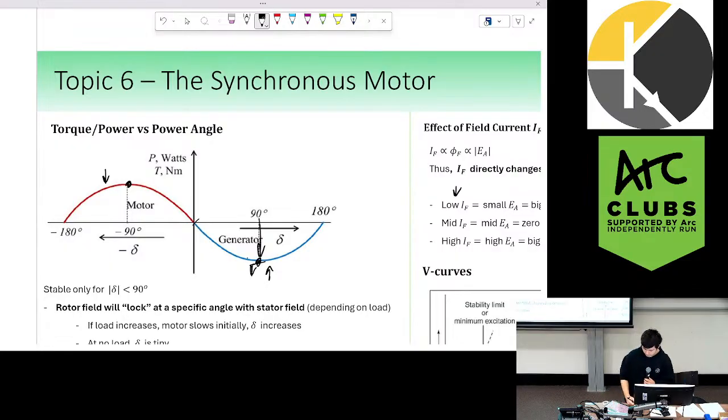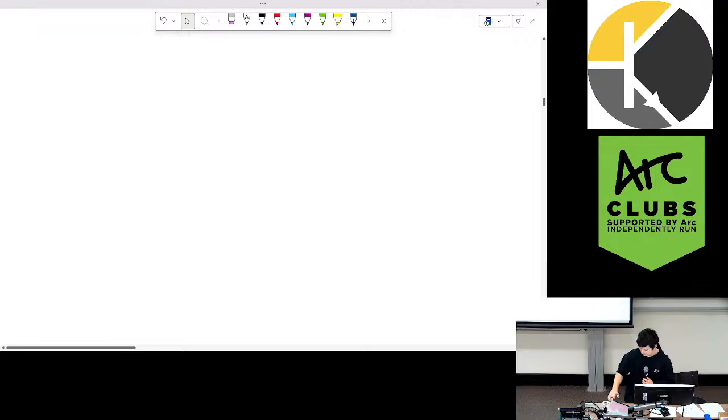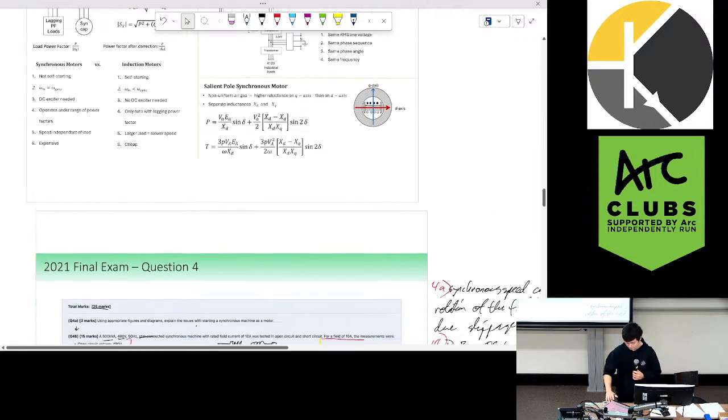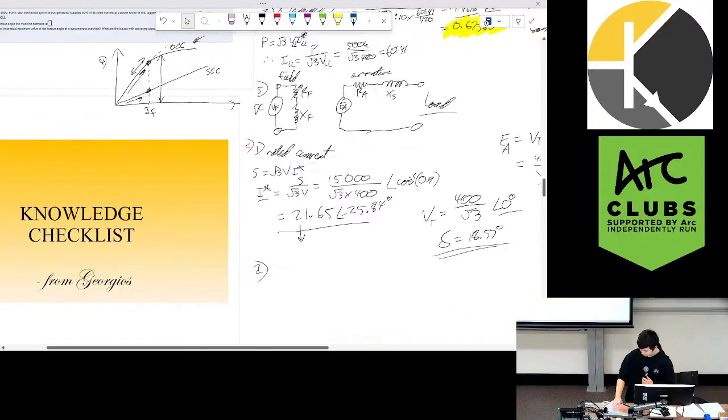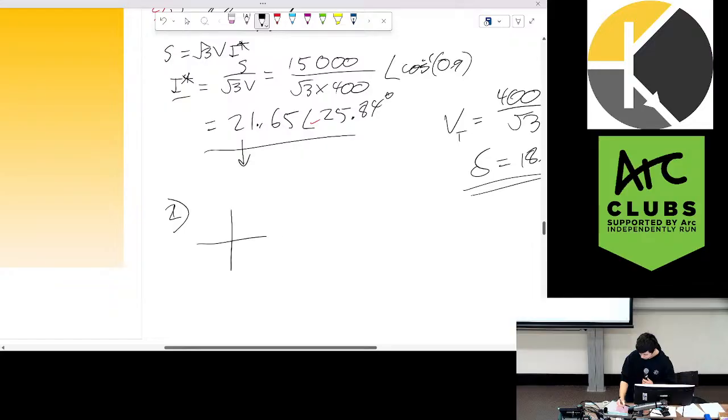So, what do we say? 90 degrees. Do we just say 90 degrees? Not technically. So, something to note is this is an electrical angle. It's not necessarily a mechanical angle. Our mechanical angle is simply when we look in between. I'm going to use an 8-pole system to consider. North-south, north-south, north-south, north-south.